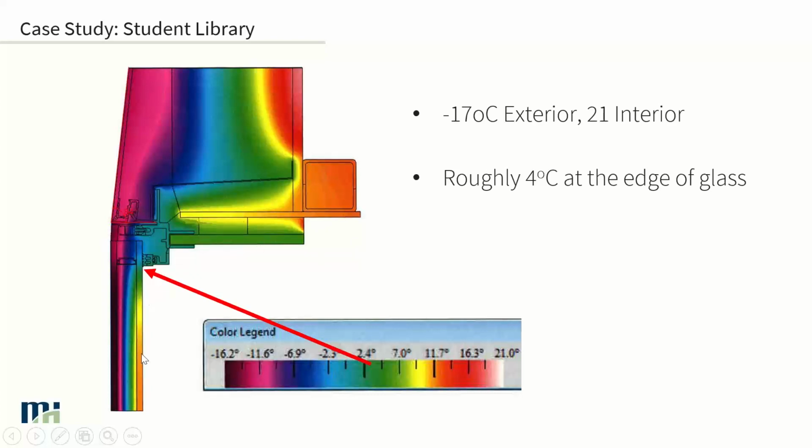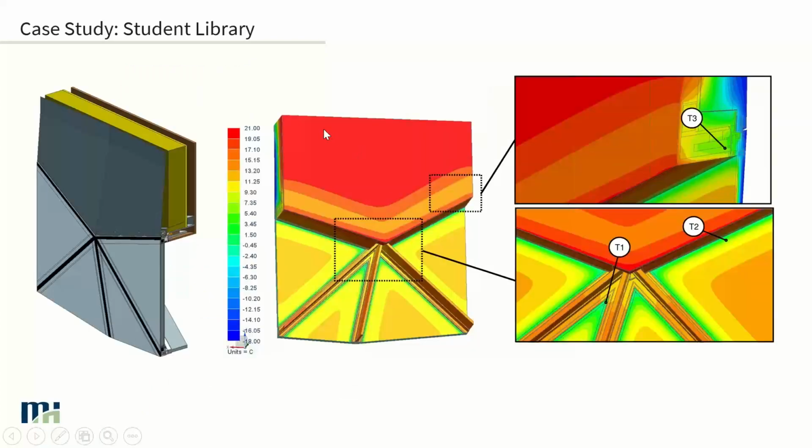And really that's because these 2D analyses are assuming heat is only able to flow in one direction through the system. It's not able to go sideways or laterally. Now, if we take that back and look at it from a 3D perspective, we're able to account for all of those mullions that butt into each other and create that larger, pinpointed thermal bridging area.